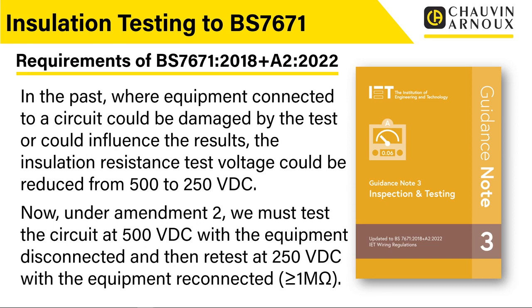Where I think this does call into question a little bit of how this will get interpreted in the real world is when we're doing things like electrical installation condition reports, where we're testing installations, particularly complex installations, where there's already equipment in service, where it's almost impossible to go around and take out every piece of equipment from a circuit. One example that always used to be talked about with this is if you've got a socket circuit with surge protected sockets. So they'd actually got surge protection built in.